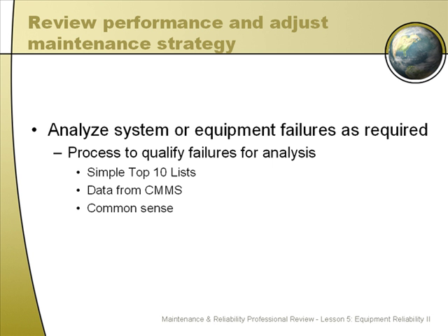If you have a failure that's obviously caused by something that people understand and it can be corrected, then no analysis is needed. But let's generate a top 10 list of failures that are occurring that really require analysis because they're chronic problems, they're very expensive or catastrophic to the program, or different special causes are making them very disruptive to your process. Pull information from your computerized maintenance management system to support this list. And last, don't forget to use common sense.